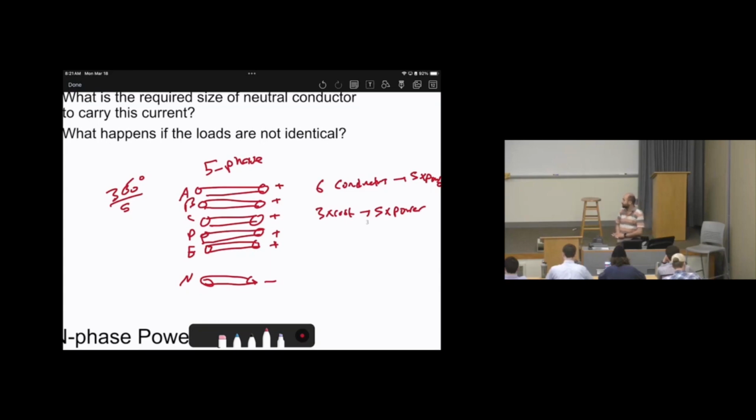Now the question is, is our electrical utility based on single phase, biphase, three phase, or five phases? Three phases, right. So why? We just said that five phase is better. Why do we use three phase, why not five phase? Because we don't really need 5-phase. None of the equipment that we operate is going to be consuming that much power.